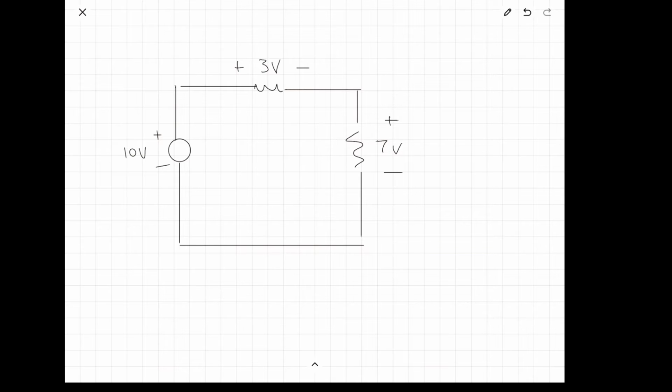So here's our circuit diagram that was on the slide, and we'll just go around it doing Kirchoff's voltage law. Probably the first step, it's not compulsory, but for explanation it makes it easier. Let's let the base here down the bottom be 0 volts. Okay? So if we go through this power supply on the left-hand side, we now know that this voltage up here is actually 10 volts. And we can think of this as climbing 10 stairs. Okay, so we're now 10 stairs up.